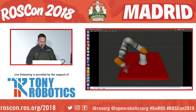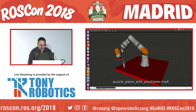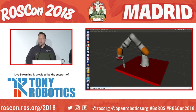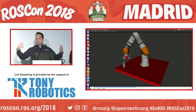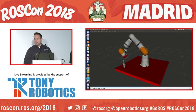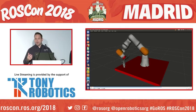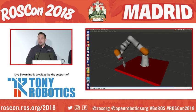And then we have another one, just to show that we added more. So say you have a positioner. You have a 2 degree of freedom positioner that allows the spindle to move. You want to solve that all together. So we created not only kinematic chain type capabilities, but an arbitrary joint tree to be able to solve that. So say you have multiple robots in your environment, and you want to optimize them all together for a complex process. By using TrajOpt, you have the ability to do that along with Tesseract.